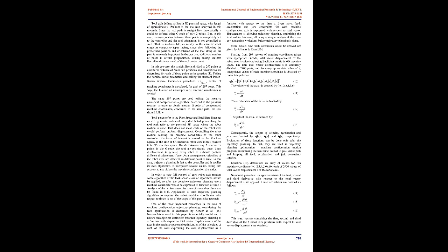There are at least 2 reasons why this approach is idealized and mostly theoretical. First, nominal robot parameters are used, and second, assumptions like the last 3 axes of rotation being concurrent, that is, they intersect at a single point in 3D space. In reality, there are always some deviations from such idealized assumptions. The point is, such deviations are quantified in the calibration procedure, so calibrated parameters should be used instead of nominal ones.